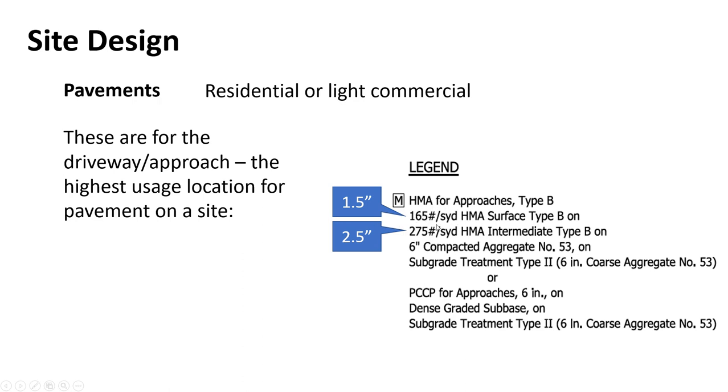But these tend to be a little bit overbuilt. NDOT likes to overbuild stuff, and it's on really good aggregate, right? And that's actually where you pick up a lot of strength. For one thing, you've got a good drainage layer there, and that adds a lot of good strength to it. So you not only got 6 inches of ag under it, but you've also over compacted that subgrade, so it's very nice and consolidated for you before you put the aggregate on, which you compact again, and then you put 4 inches of asphalt.